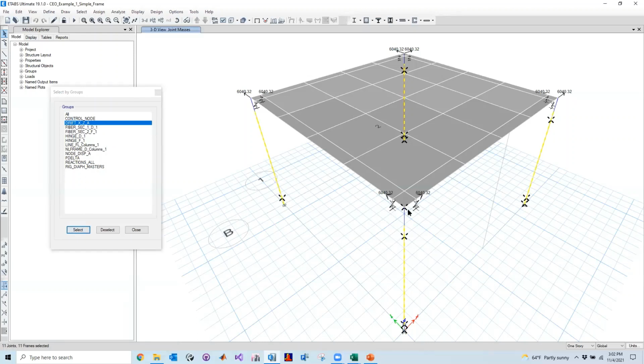So here, you can see the drifts are recorded at these 2 nodes over here. That's basically how you would select. I guess I forgot to deselect them. So I select drifts. There's only these 2 nodes, top and bottom, right? And that will be a drift at that point. So drift xz means drift in x direction, and z will be a perpendicular direction to whatever direction you want to record.